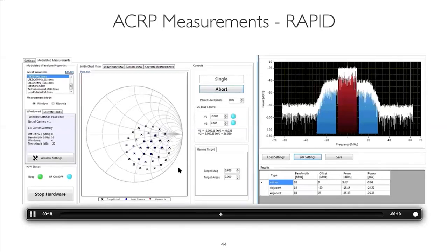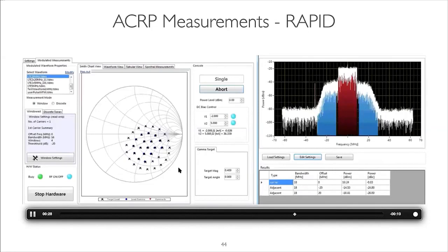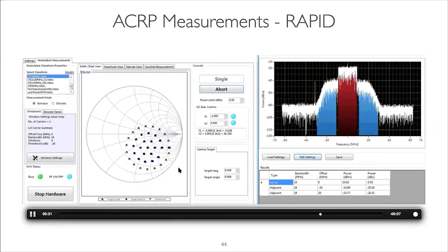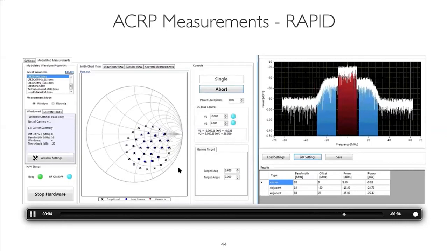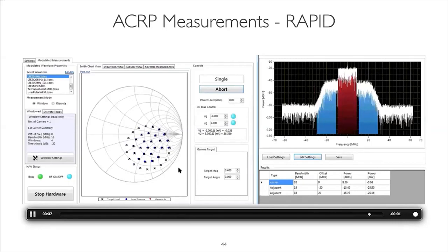Same thing for the load pull accuracy. You're using a very broadband digitizer to measure, and you're re-injecting this broadband signal. So you end up reducing the dynamic range, versus if you were using a CW signal where you have greater than 60, in certain cases greater than 80 dB dynamic range. But again, this is ultimately if somebody wants to have a very controlled impedance. What we're seeing here in the load pull is we're not presenting a skewed impedance like a passive tuner. We're really controlling the impedance across the entire bandwidth, setting a single point. Okay, so for some customers, this is crucial. You want that fixed impedance, measuring ACPR accurately and measuring EVM.